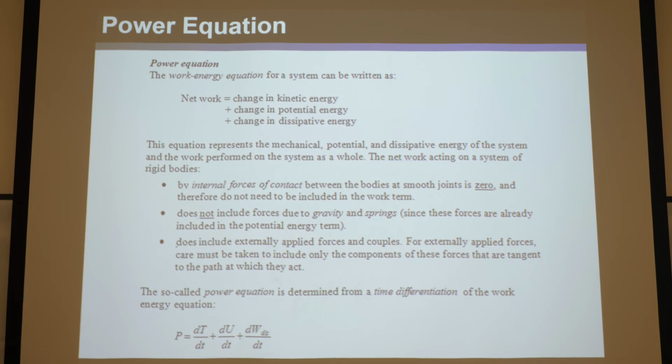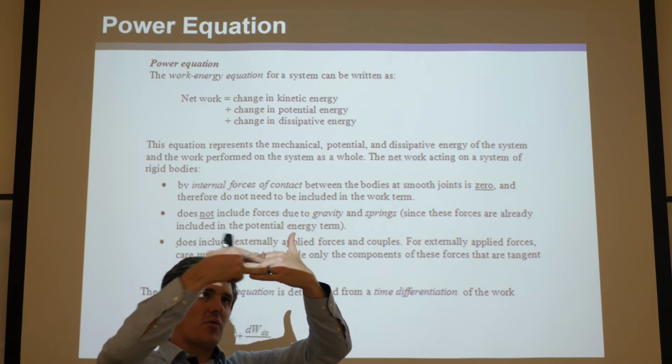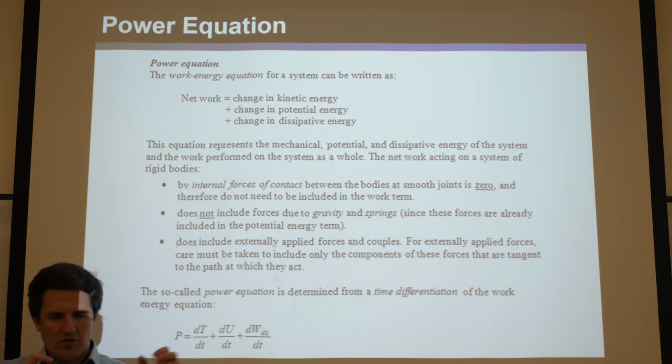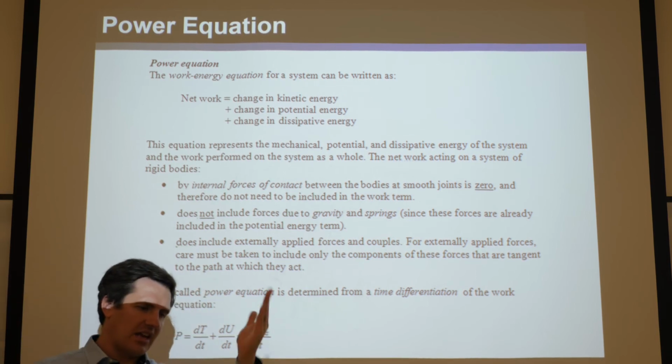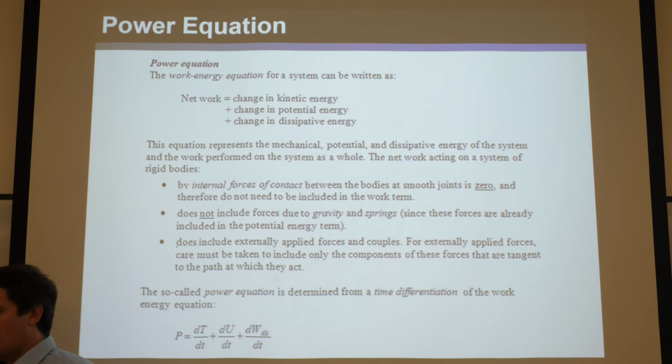But what this is saying is the internal forces at the joints. If you have two links stuck together by a pin joint, this one's putting force on that one, and that one's putting forces on this one. Or if you cut a beam, a link, in half and you see the internal forces from the stresses inside, you don't consider those internal forces that are going on in the mechanism to keep it from falling apart and to keep it working together as rigid bodies in a mechanism.